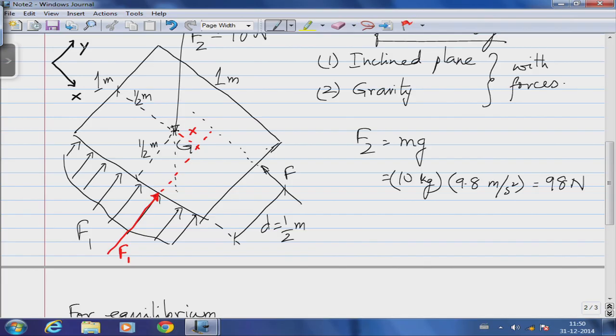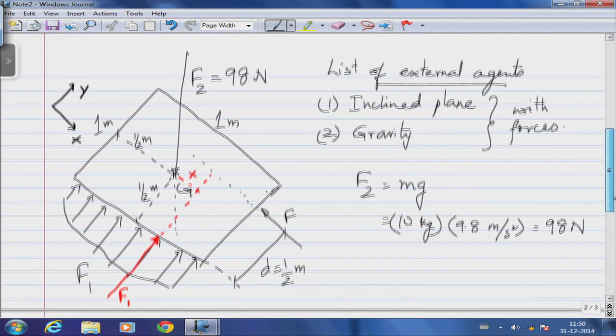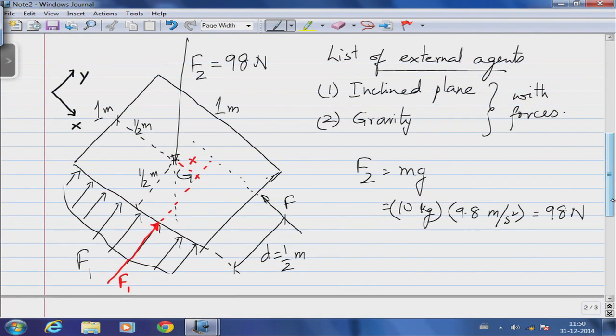If you notice, I did not define my coordinate system first. I am defining it at a point where I have to do the force computation, because I can look at the forces after I have drawn the free body diagram and choose a coordinate system that would require me to resolve the least number of forces as components.